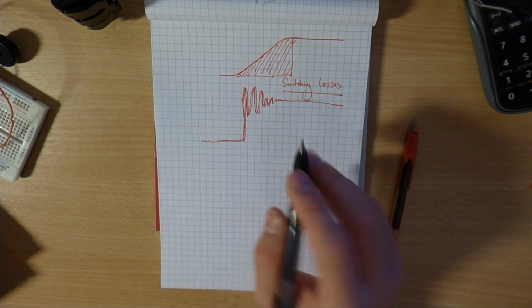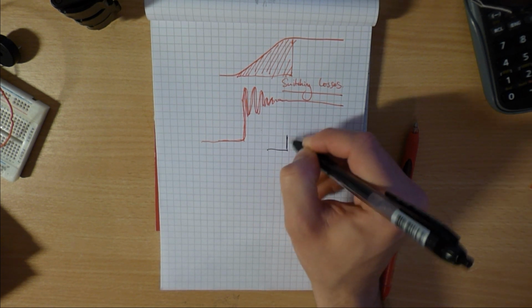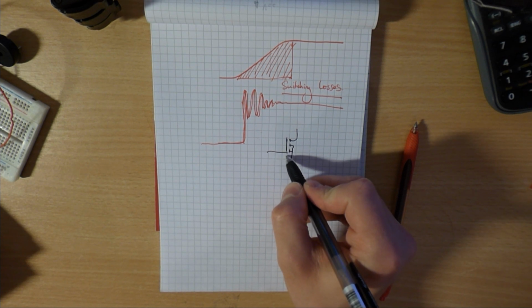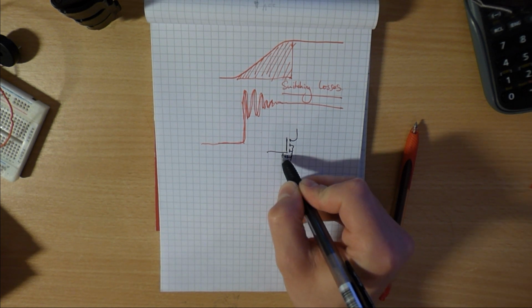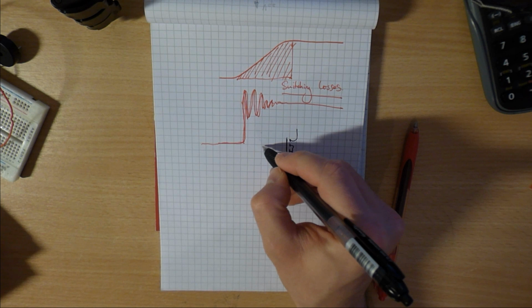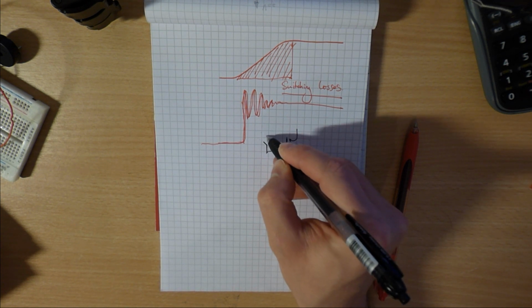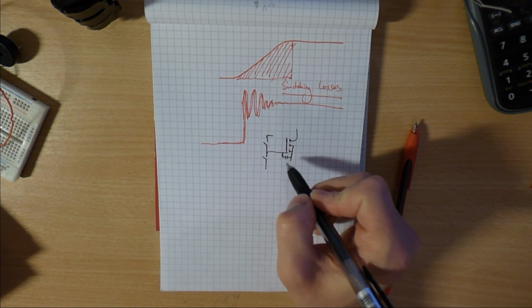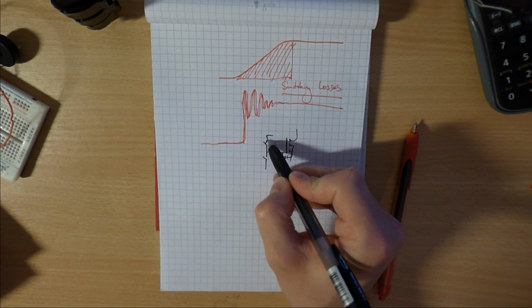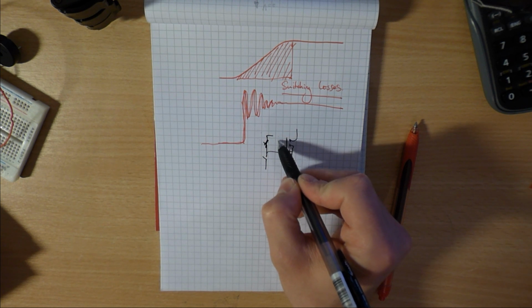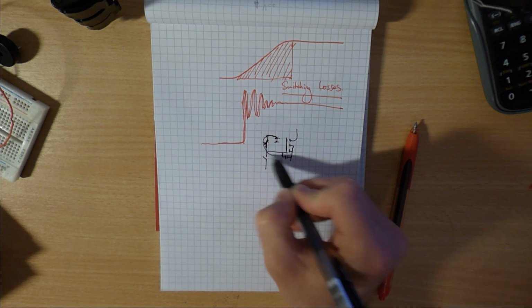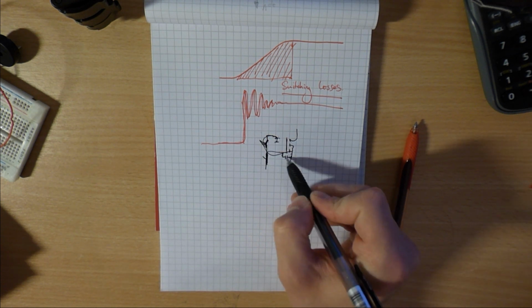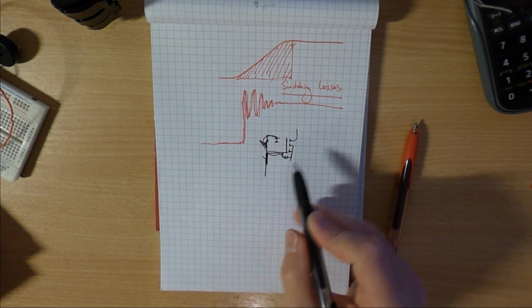It also has the benefit of, if this is your gate, let's just do that like that, discharging this capacitor very quickly as well. So if you imagine the totem pole arrangement is like this, we can either switch this output here, and this goes to the bootstrap capacitors and it can charge it up very quickly, or we can open and close this switch and discharge this capacitor to turn this off very quickly,